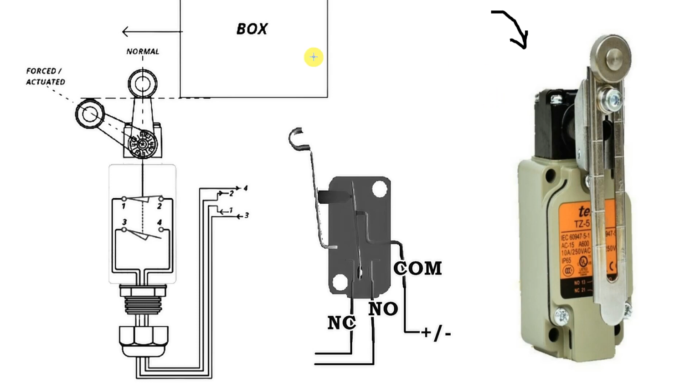Now, limit switches are contact-based sensors, and they provide an output signal if and only if the object to be detected makes physical contact with the sensing element of the limit switch, which is also known as its arm, right? After the contact, the arm has to travel a certain distance before it goes into the actuated state, and then it will generate an output signal.